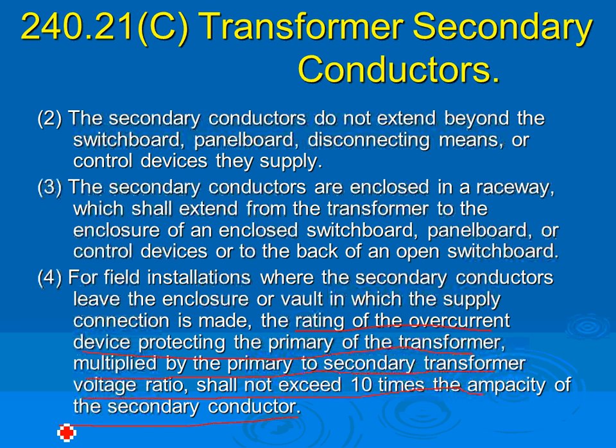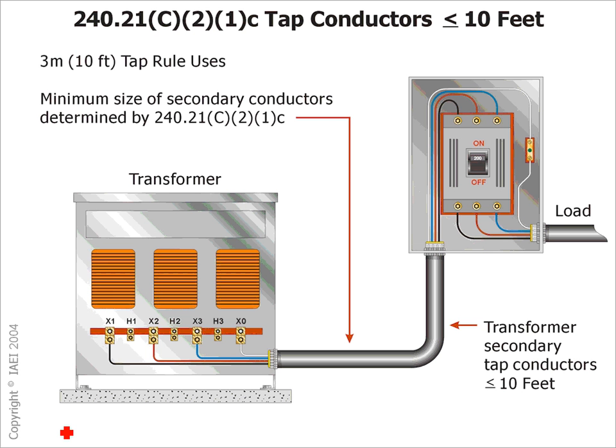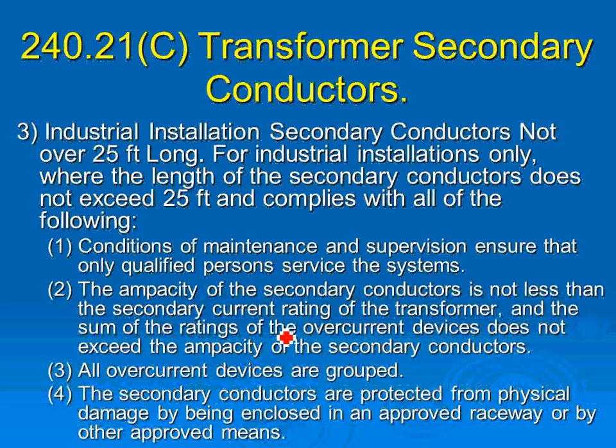Any comments, guys? Any questions about that one? So that's my conductor on the transformer secondary. We talked about that, and we take advantage of this one all the time, guys, when we size the receptacle panel. That's how you get away without putting a fuse right in here. Otherwise, we have to put a fuse right in here at the source, the fuse disconnect, right at the source.